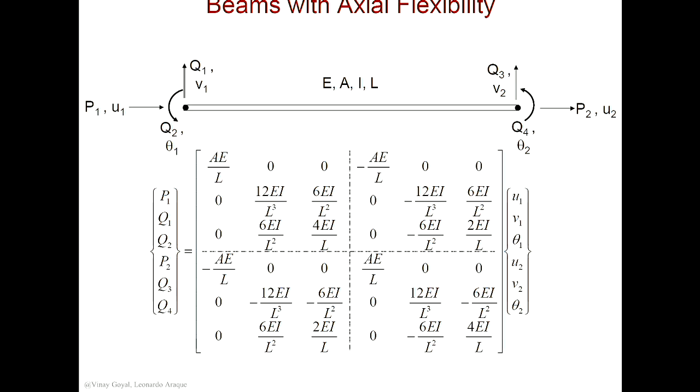I can make it into composite material. A composite material, if you have an asymmetric composite material, right, then you can have coupling between stretching and bending. Okay? As long as it's isotropic, it's not coupled. In this case, fully isotropic. So in this case, there's no coupling. But we can make it very coupled, very quick. Okay? All right. Any questions?